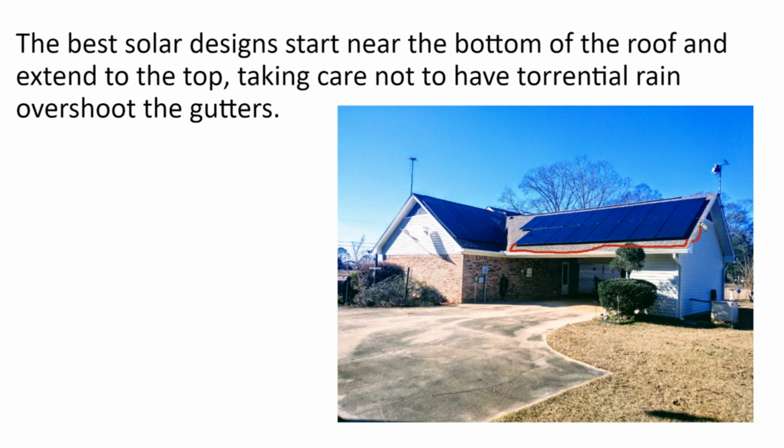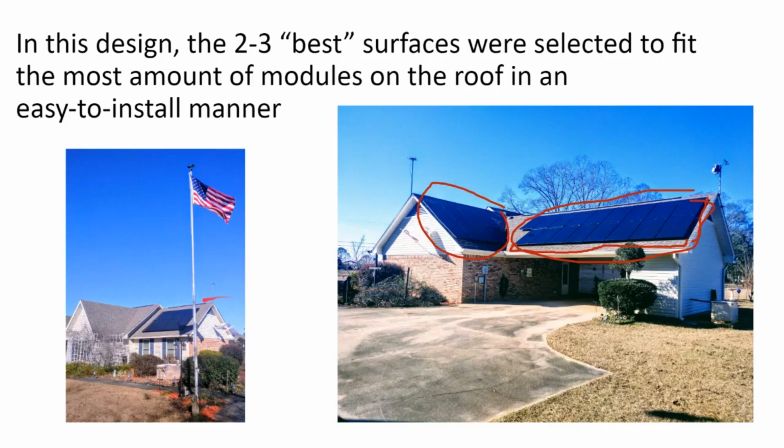Personally, I would only bother with roof surfaces that can fit 8 solar panels or more, such that the installation crew can work efficiently and a good installation price can be obtained. A pallet of solar panels is between 20 and 30 panels, and a good-sized residential project can be 2 pallets, which is about 15 kilowatts.